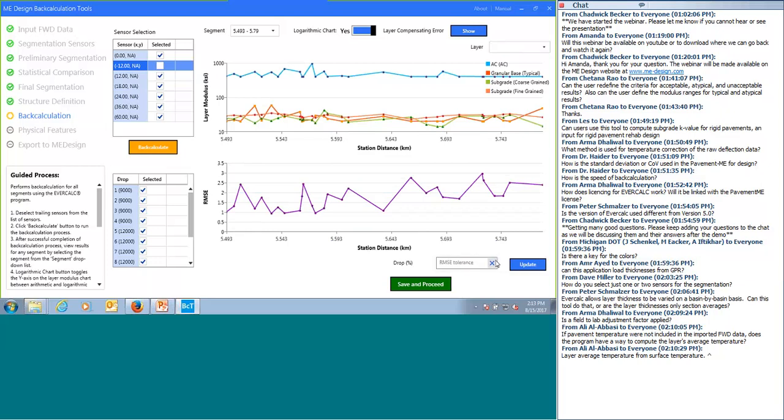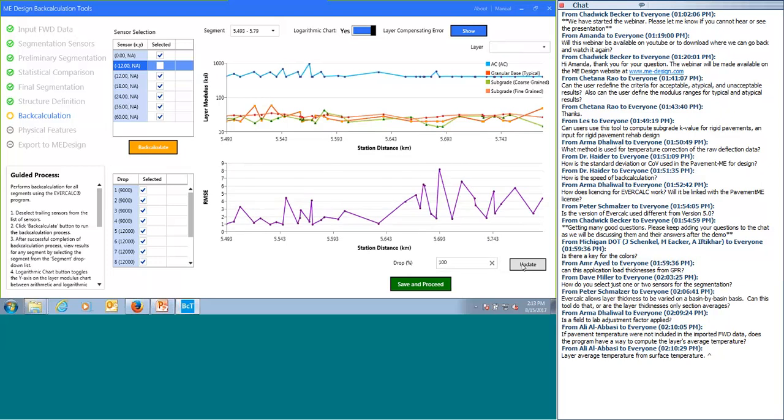I'm going to leave it right now at not really having a tolerance, and we can see that we have quite a few values on the lower end that are much greater than 5%. A lot of values are greater than 3%. Remember, less than 3% is very good, and greater than 5% we probably don't want to use. So that means I need to change my structure simulation.